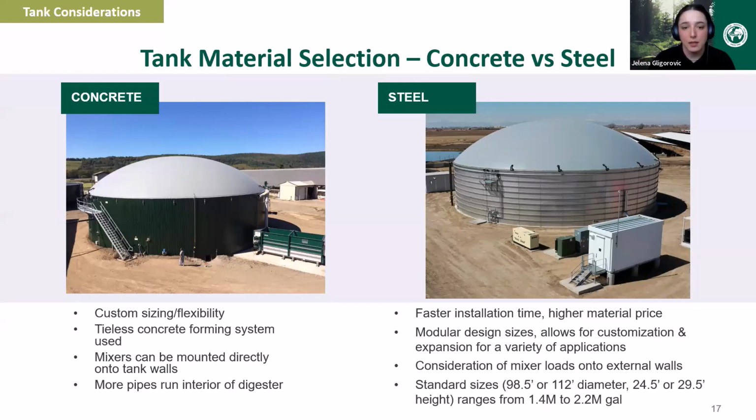On the steel side, steel tanks are usually installed faster. They are a little bit more costly than concrete tanks. However, they are easier to install in colder weather, in winter conditions. So depending on the construction schedule, this might also determine whether you go with concrete or steel.